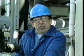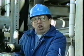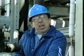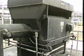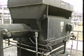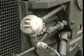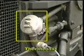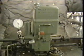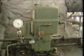In addition to anti-surge protection systems, other safety devices are commonly installed on centrifugal compressors and their auxiliary systems. Drivers, for example, must have their own protection devices to prevent them from being damaged by overload conditions. Electric motors are protected from overloads and overheating by thermostats and circuit breakers. Turbines are protected from overspeed damage by governors and overspeed trips.